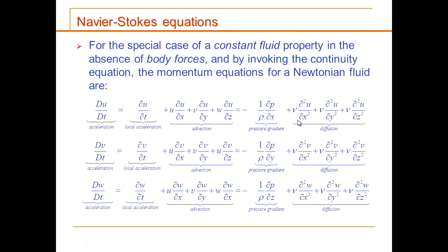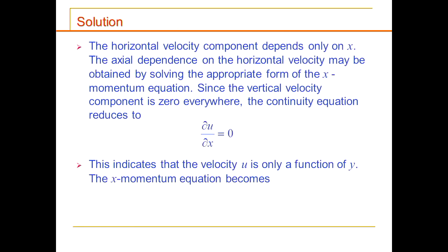Imagine if you have a super large Reynolds number, then your diffusion term doesn't really matter. It becomes a very small number. And if you have a very large advection in comparison to your diffusion, then whatever velocity you put in will be equivalent to the velocity going out. So that's why your outlet profile retains its shape when your flow is turbulent.